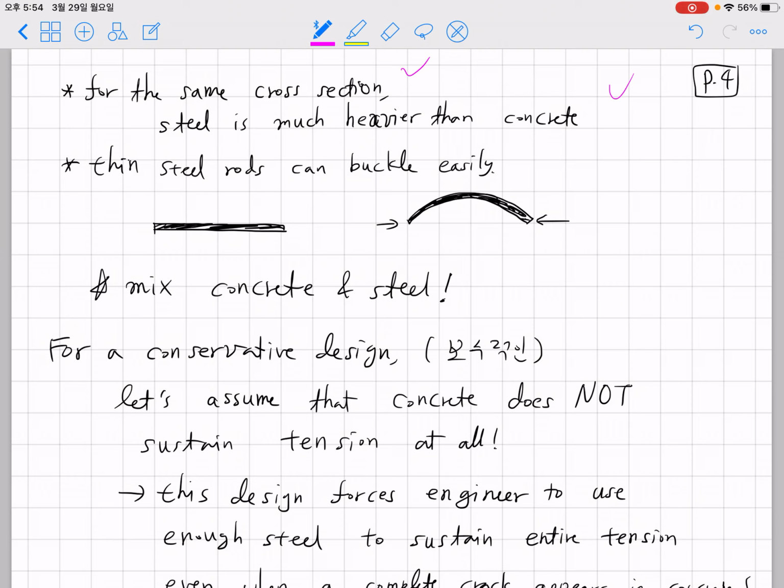If we build a really thin building only out of glass and really thin steel beams, we're not gonna have good enough thermal insulation. And if we make the building too thin, it'll be quite weak under earthquakes. So we anyway need a little bit of volume and mass based on concrete.